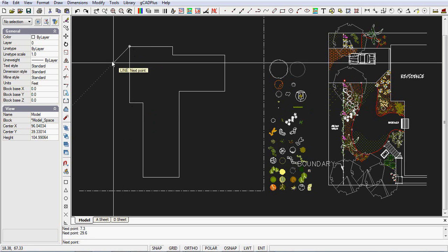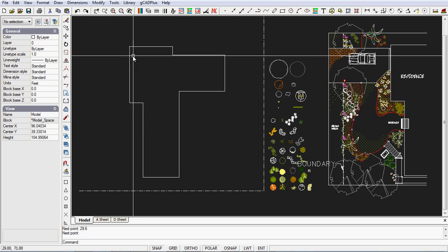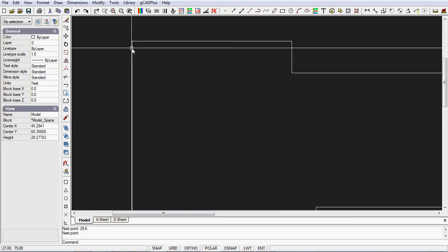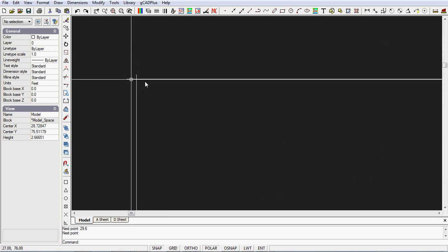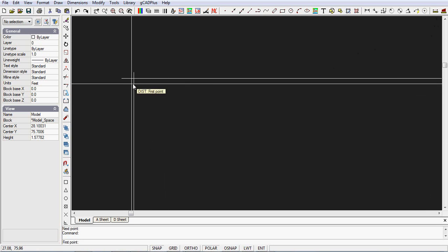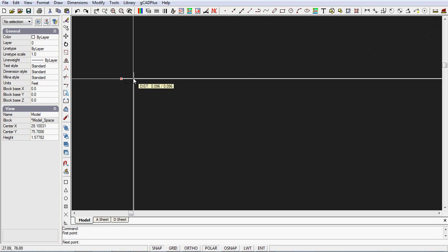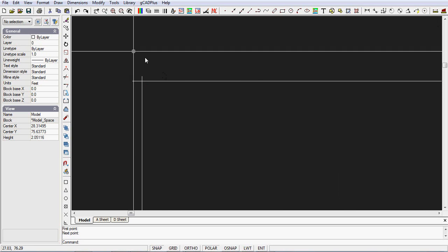Now right click to finish. If the mud map's been perfectly accurate, these two end points, where the start point and the end point should meet, then you can see there's a very slight difference. We're slightly out in the measurements. Let's just check how far out we are. We're 0.1 of a foot, so I think most of us would agree that's more than accurate enough.